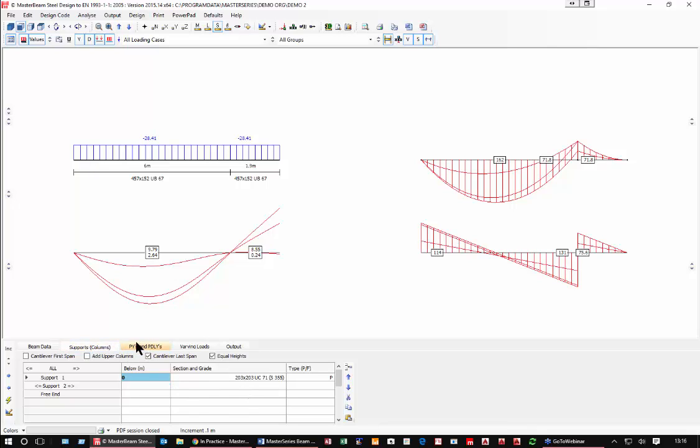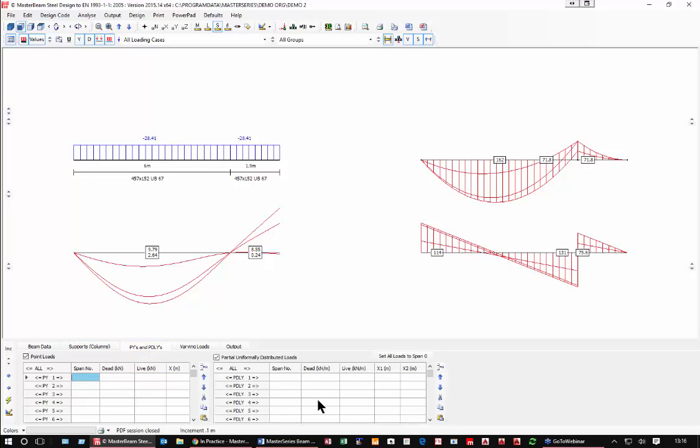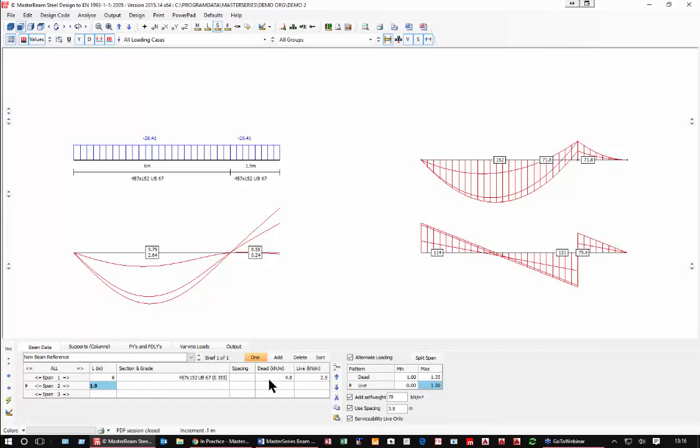We can now come along to the third tab and we can put on our additional loading. We've got our blanket load, and if I come back actually to that, I apologize, every time I put a value in here, if I don't change it, it's the same. So if I wanted a lighter load on the balcony, I could say that the balcony has 1.5 kilonewtons of live load, not 1, but that will still be the 4.8.